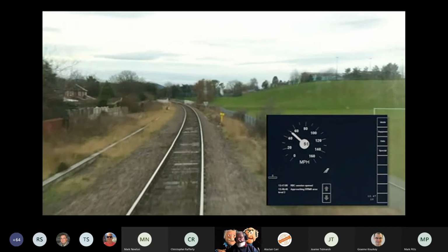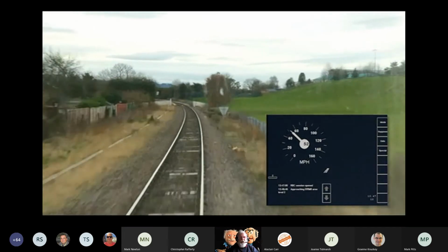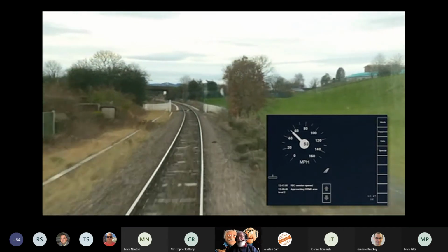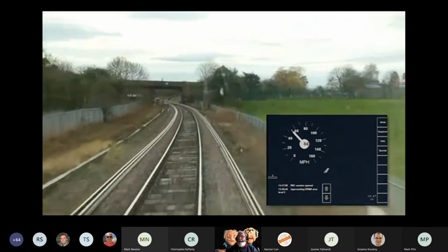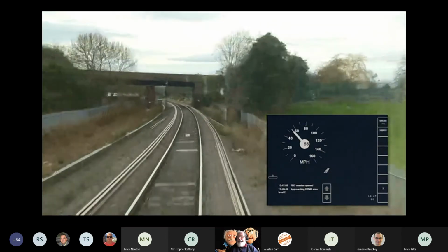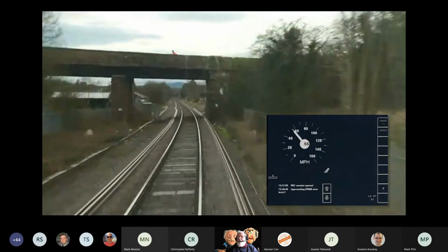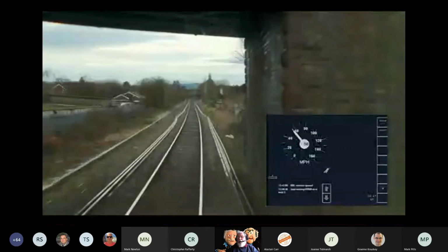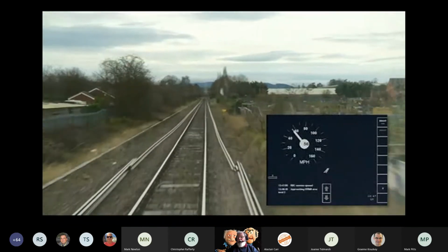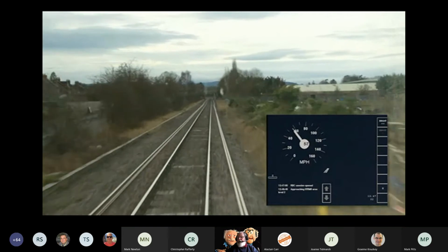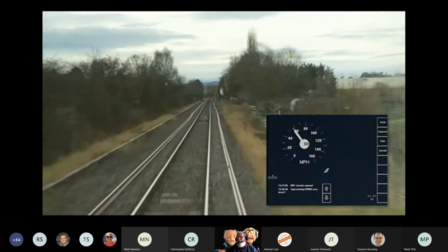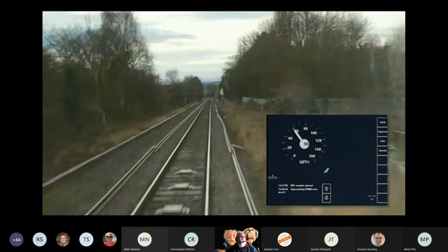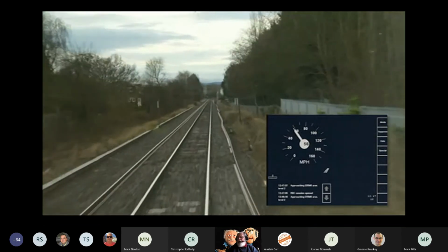And the session has now been opened. And in ETCS baseline 3, that will be illustrated by an icon appearing. There is time allowed for that session to establish before the announcement of the transition occurs. And in this case, it is sent by a set of balises. You'll see 4 balises which we're just approaching, 1, 2, 3, 4, which duplicate the message.